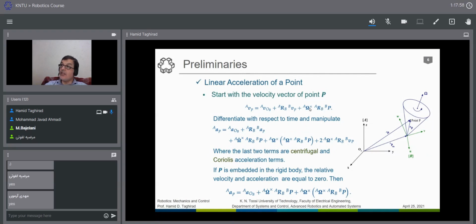Now we have here a three-term product, and we would like to get the derivative. So we have three terms here. First, just the derivative of this times this, you can see. Then, the derivative of this times this, and the derivative of R B is omega cross R. You can see it was omega cross R times B. And finally, the derivative of this. Then we have a relative position here. The derivative of that gives us the relative velocity. If one term comes from here, these two, we have omega cross R times the derivative of that.